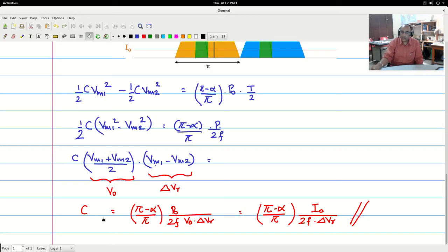Another very important criterion that you will have to take into account while you are putting the value of C in a real circuit is that when you buy an aluminum electrolytic capacitor, it has a very large tolerance, minus 40% to even 100%, those kinds of tolerances. So what you calculate, and then what you buy and actually measure, can have a very large and significant variation.